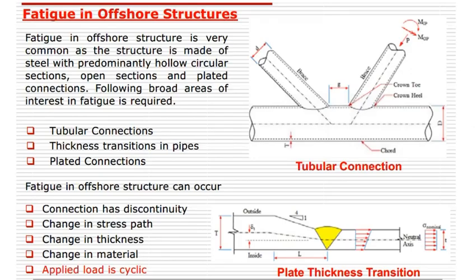Fatigue in offshore structures is very common, as the structure is made of steel with predominantly hollow circular sections, open sections, and plate connections. The broad areas of interest include tubular connections and thickness transitions.